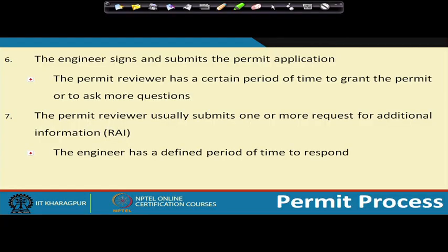For a very small work, probably maybe, but most of the work is done through AutoCAD. Still, the AutoCAD drawings have to be printed out and sent to site, and the site people will do the construction. At site you cannot have the drawing on the computer and try to use it. There may be, these days, high-tech automated construction, but I think 99% of construction is manual construction, where you need to have that physical drawing so you can check each and every aspect of the drawing while the construction is going on. So for the construction engineers, these drawings are very important, and also to understand how the plant will look. That's why drawings are made at 30%, 60%, 90% levels.